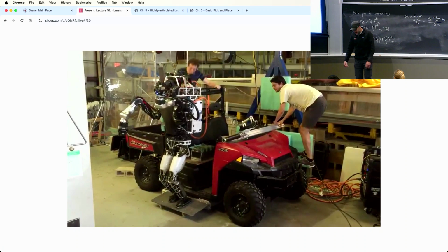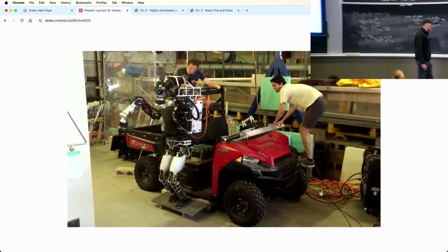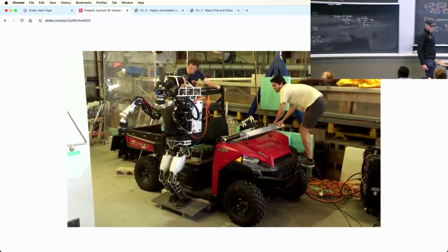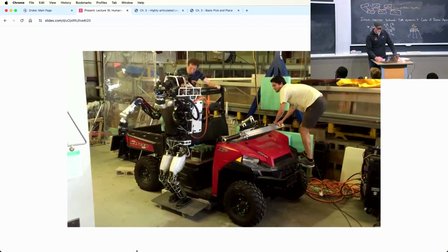So it turns out that it's actually fairly simple. We weren't doing LQR in this. We're doing kind of the one-step version of LQR that was trying to regulate the nonlinear dynamics, but everything's simple when you're just doing one step. And you can write a small quadratic program, basically, that balances the robot and gets the job done. Except on the day of the competition where you fall down once. But no, it's a pretty darn good controller.